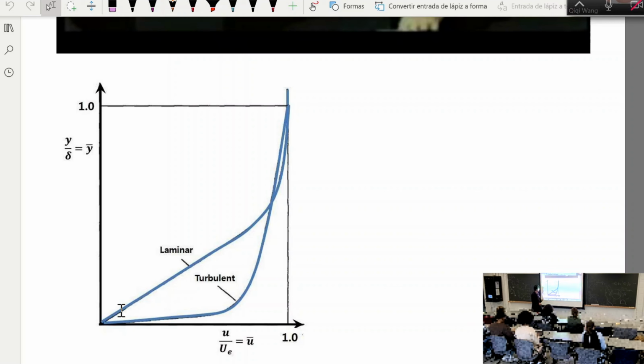For the turbulent boundary layer, it's very much not the case, right? As we have derived, the velocity gradient near the wall is very, very high, very steep. And as you go away from the wall, there is turbulent mixing, and the total viscosity increases, and as a result, the velocity gradient decreases. So you typically have a boundary layer profile that goes like that, and then like that. So the velocity gradient is changing all the time, going from the bottom to outside.